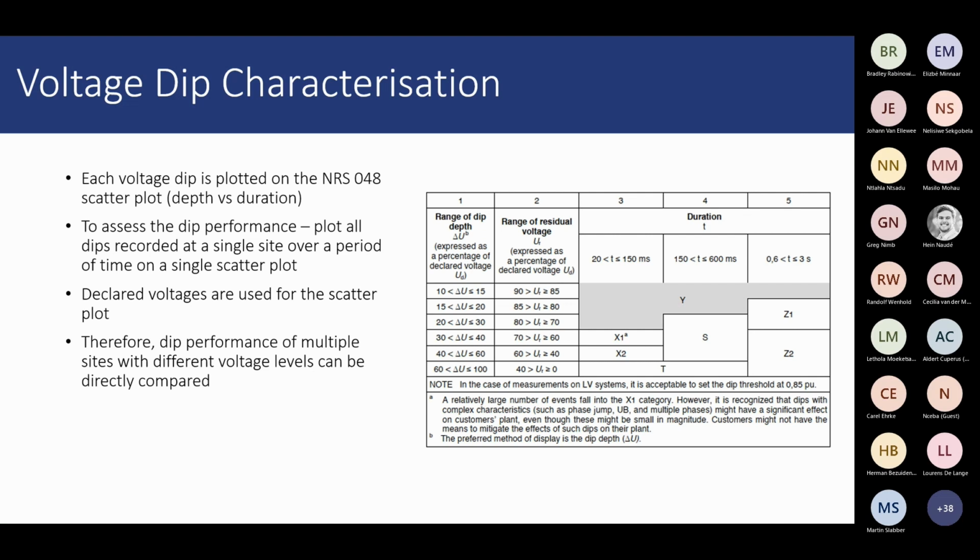When one tests the alarm systems to go out, for instance, I've tried to simulate the trends on all the monitors we have on voltage regulation, balance and harmonics. Have you guys ever tested those alarms if they go through? Because if you were to take Omicron and inject the voltage, keep on dropping the voltage almost to 40%, most of the instruments only respond up to 40%, but that's way below the lower bound of the voltage regulation. So I heard you talking about the dips. Do you have any suggestion how one would test the dip threshold exceedance?